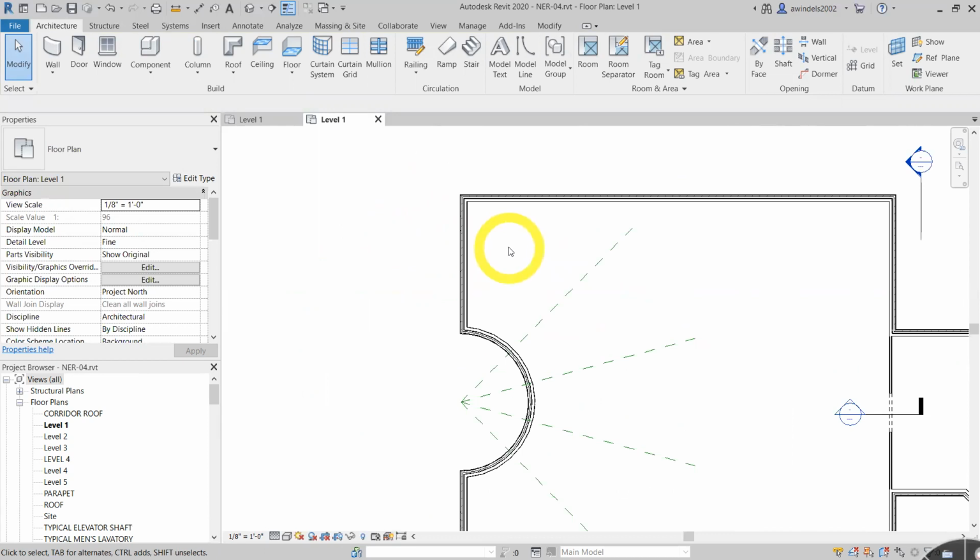Let's see what they want us to do. We're going to add 2 reference planes. And I'm seeing how to add those quick. So the picture on page 186 is pretty helpful. We're going to add them with the line command with 2 picks. And we're going to add 1 as an offset of 1 feet 6 inches from the upper left corner of the intersection. So let's start with that reference plane.